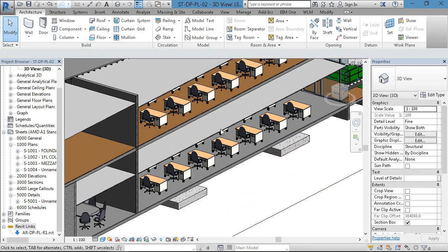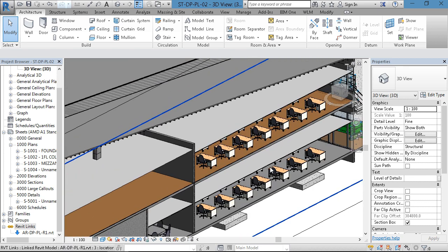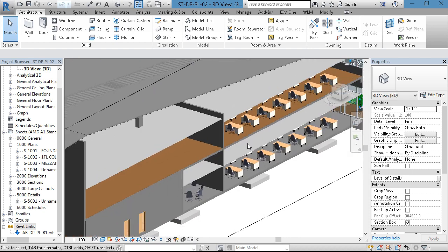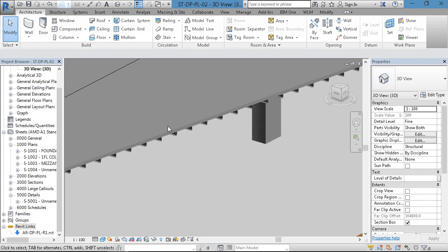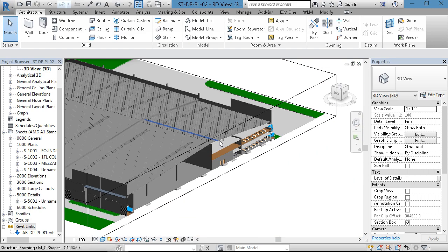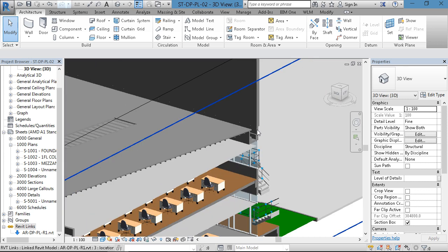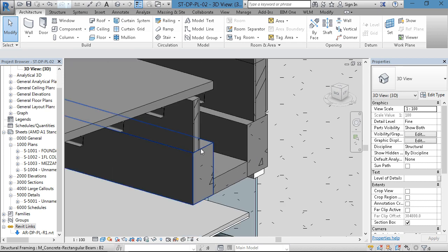So I have the ceiling here. In the architect model, we have furnitures for MEP to design their AC diffusers. So I have the roof already, and you have those purlins. So now we have the concrete gutter here. So I just put this one as a beam, this one is a slab, and then I just put a brick wall here so that water cannot go inside.